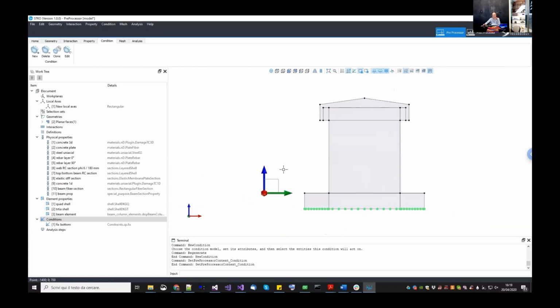The user thinks that it is assigning a surface load or a load distributed on an edge or on a volume. And in STKO, we directly do the nodal lumping while we are writing the Tcl file. So you assign a load on a surface, and when you write the Tcl file, we write the equivalent nodal forces for OpenSees. This is very, very useful.